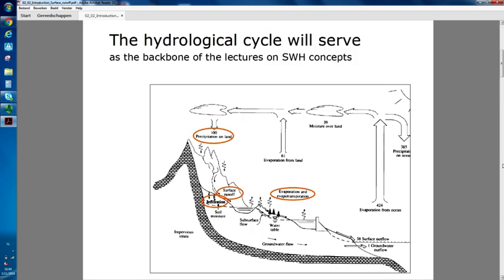As we have seen from our theoretical lectures, we know that precipitation is the main driving force of our hydrological cycle. The water falls onto the land, but some of it is lost and cannot travel towards the river. Partly it is lost by infiltration, partly it's lost by evaporation and evapotranspiration, but also other losses like initial losses, depression storage, or for example interception, account for some losses of rainfall and lead to the amount of net rainfall.